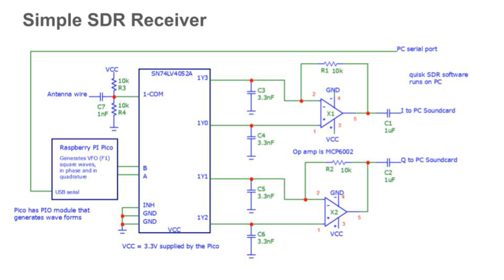Its job is to shift a region of radio spectrum down to the audio frequency range. The resulting I and Q signals are amplified by the op-amps set up as differential amplifiers. Again, see my previous video. The I and Q signals are then fed into the two channels of my PC's sound card. The sound card converts the analog signals to digital form. Software on the PC filters, demodulates, and otherwise processes the signals, and the result is a radio receiver.